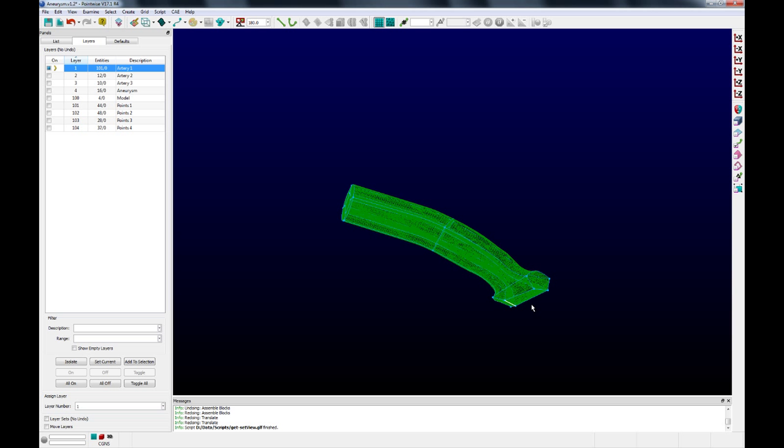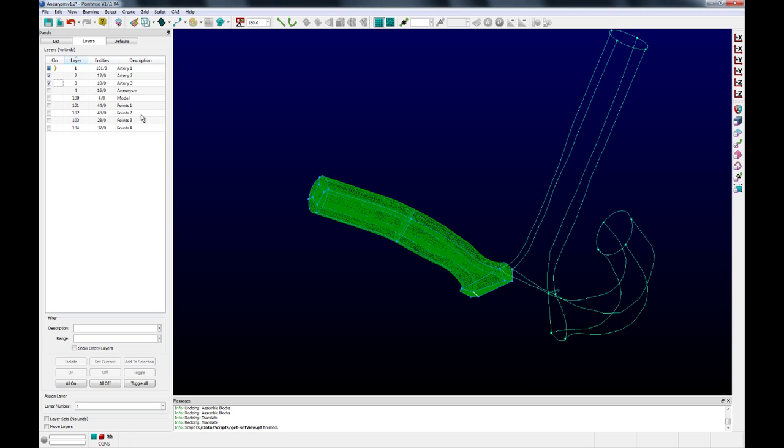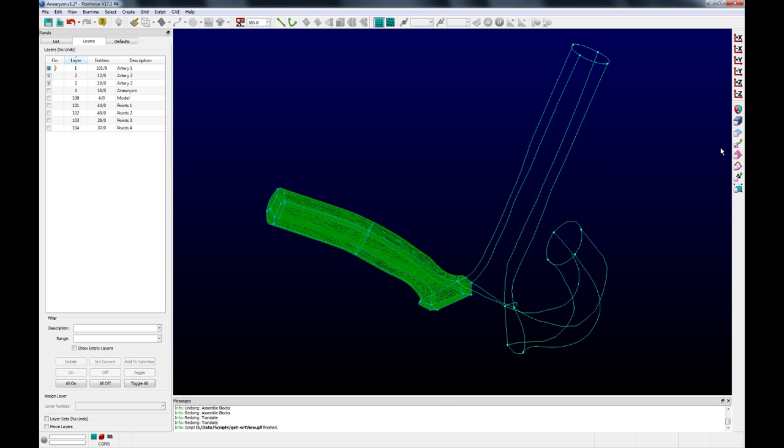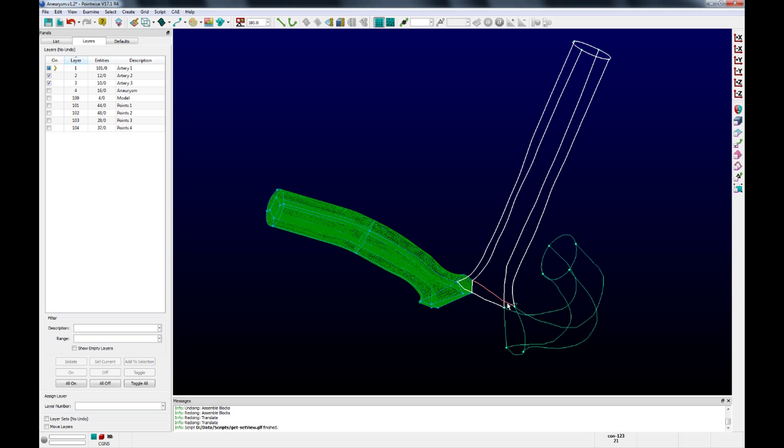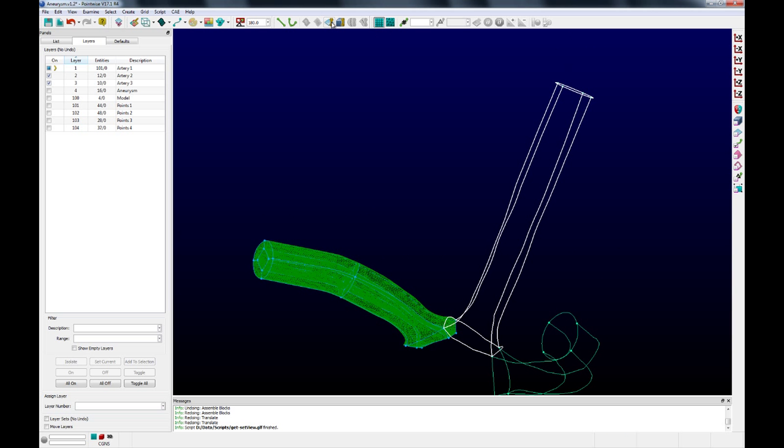So what I'm also going to do is showcase how you could do this in one step with another script that we're going to have available on the script exchange as well. In order to use this other script, we're basically going to just highlight these connectors. We're going to create essentially one H block for the entire artery. So I'm going to use this artery here at the top, and we're just going to select all those connectors and click on assemble blocks. That's just going to create a regular H grid on all of the connectors here.